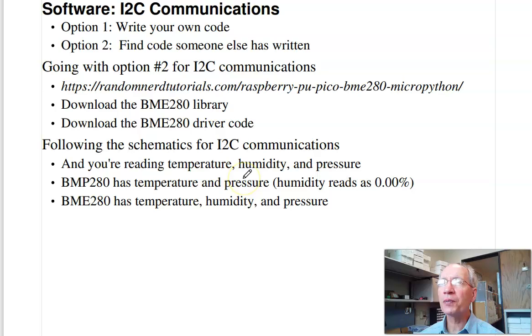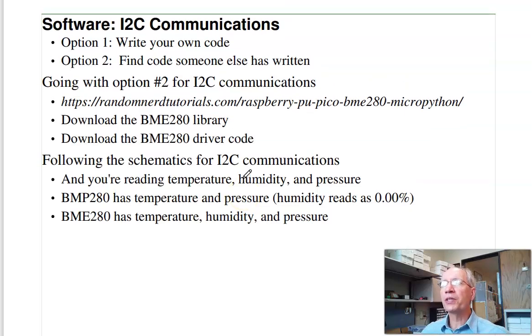In terms of software, what you can do is dig through the data sheets and write your own code, or hope that somebody else has written code to drive the sensor and use their code. Well, if you go to randomnerdtutorials.com, there are drivers for the BMP280 sensor using the I2C interface, which is why I'm using that.